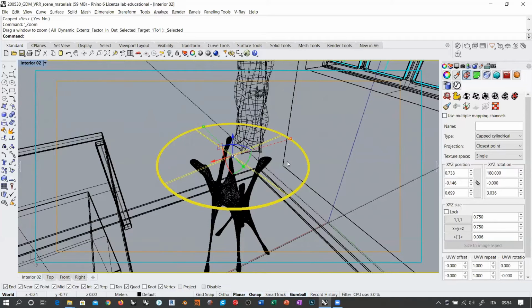Okay. So general rule: if you want to spread texture all over the surface of an object, then you can use automatic mapping if there is one that is suitable for that particular shape. But if you want to place a texture in a specific spot, you cannot use automatic texture mapping like any of these widgets here. You have to create a custom texture mapping. So first things first, we must create a custom texture mapping for this object, okay?